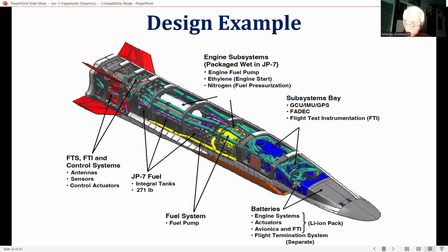But the primary ones of the choice are Newtonian, modified Newtonian, tangent wedge, tangent cone, and shock expansion, all discussed today. Methods used for the prediction of shear stress and heat transfer are also discussed today.